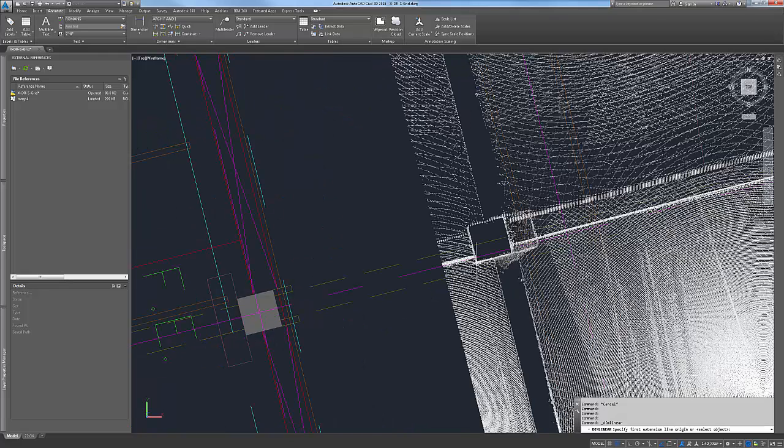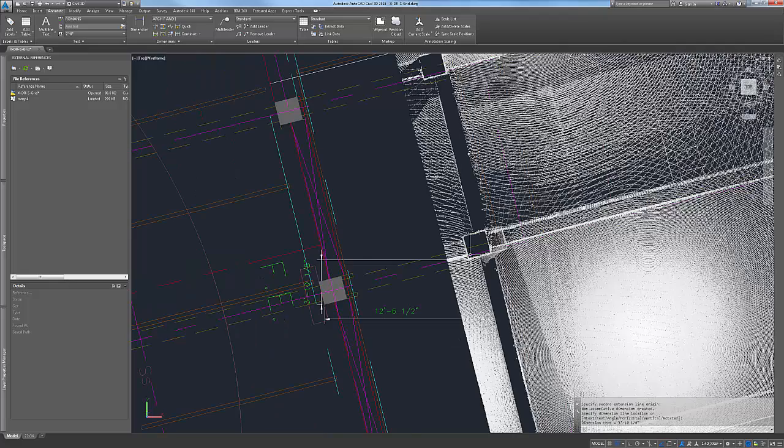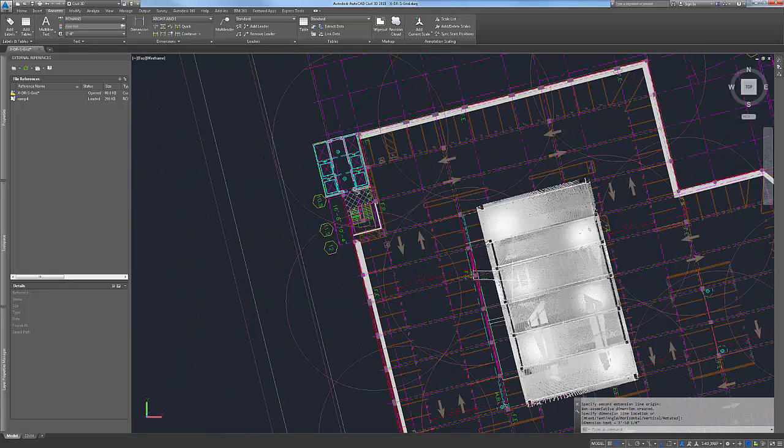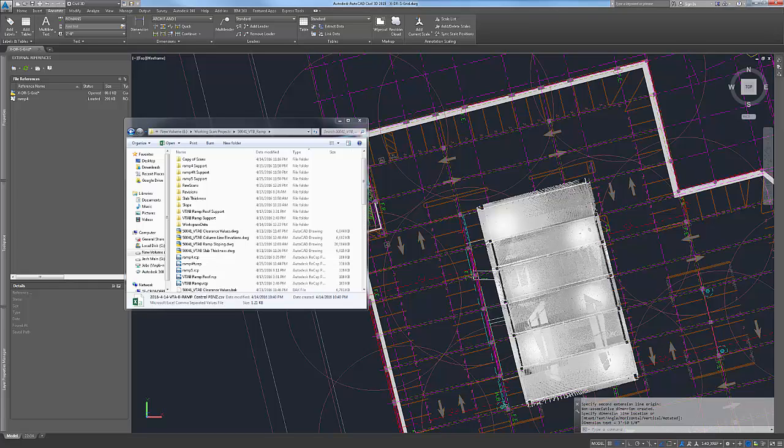The simplified answer is the conversion factor when going from US survey feet to metric units. Metric units is measured by international feet or regular feet. So we're going to take a look at our CAD file or our control file and notice that our control file coordinates are rather large and they're in state plane coordinates. Our X values start in the 6 millions and our Y values start in the 1.9 millions.